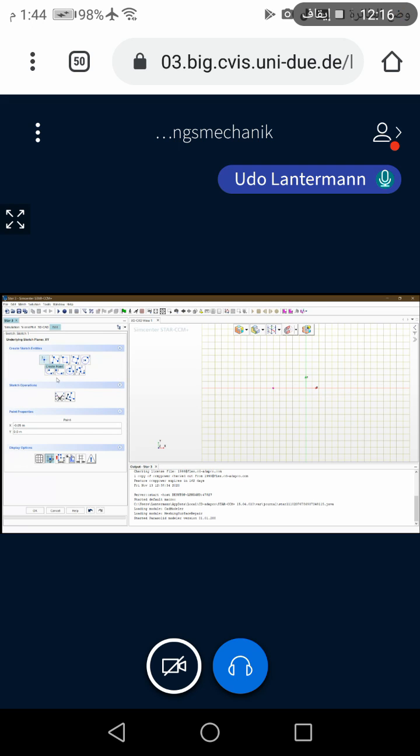Okay, then we will create the next one in the same manner. So again, click on this first symbol with the points and choose again, set the point somewhere on the grid. And again, click on the point so that you get the coordinates. So the second one will be x direction minus 0.5. And y direction is again 0.